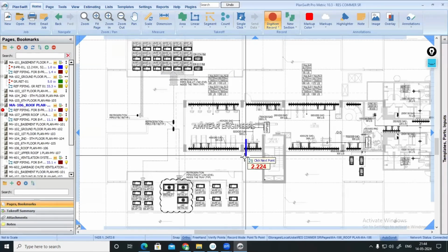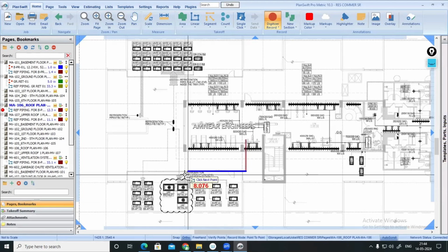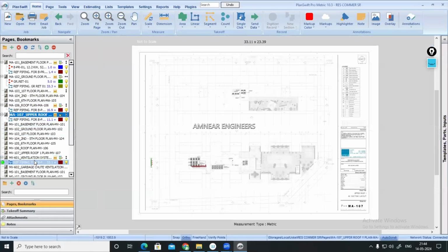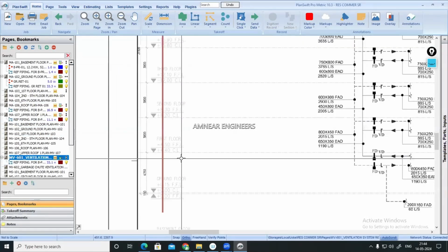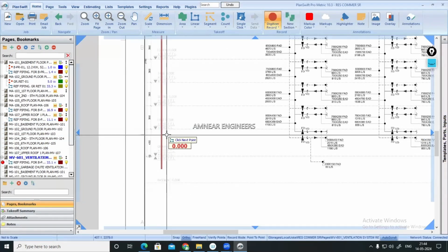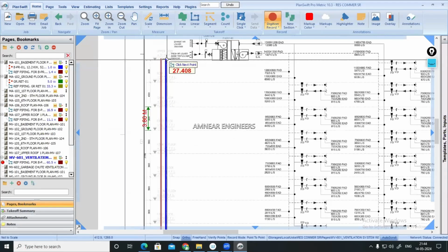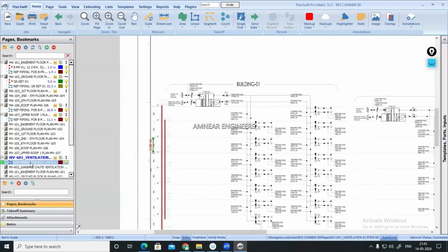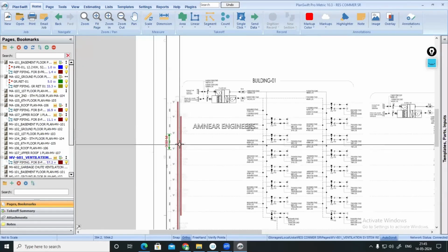This is roof plan only. So you can take like this way, then like this way. Then you can VRF retail. Approximately this much length of horizontal will come. Plus, this is from ground floor. I'm just going to the refrigerant piping. Now it is from ground floor only. Refrigerant piping for this one. Ground floor somewhere here, ductable unit. Ground floor to not upper roof, ground floor until the roof level. Okay, so this much vertical piping also will come for that machine. Correct. So horizontal and riser also I have taken.